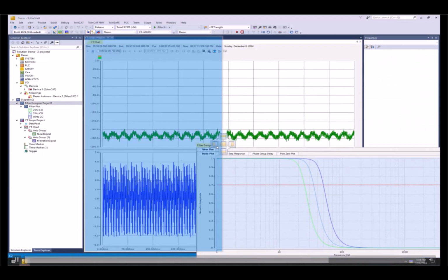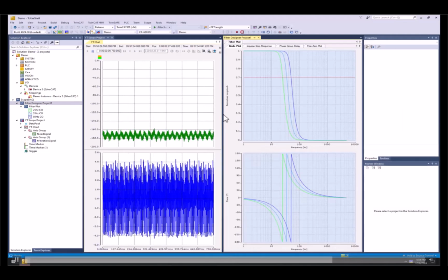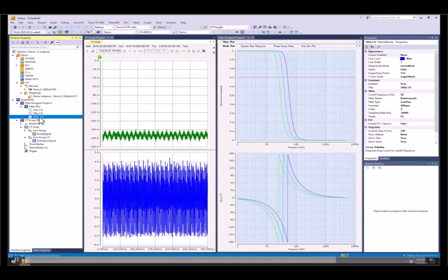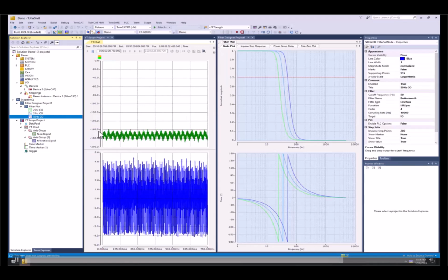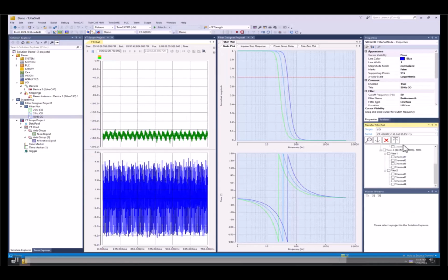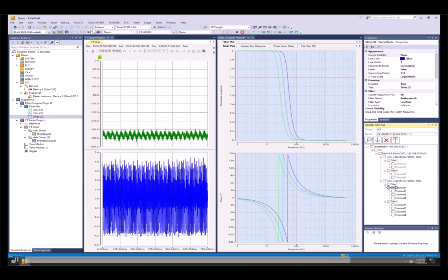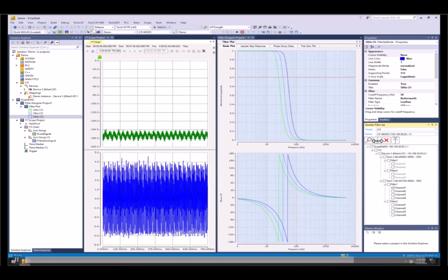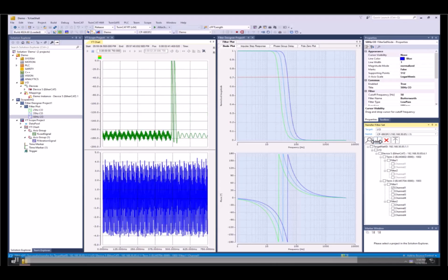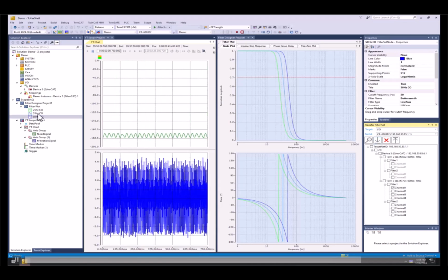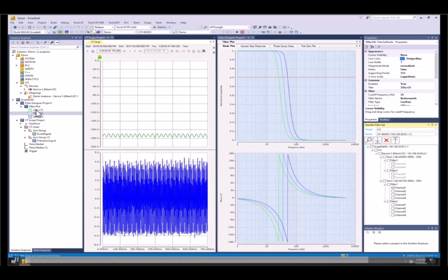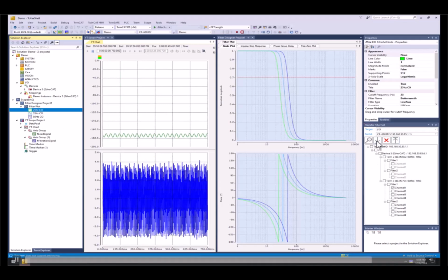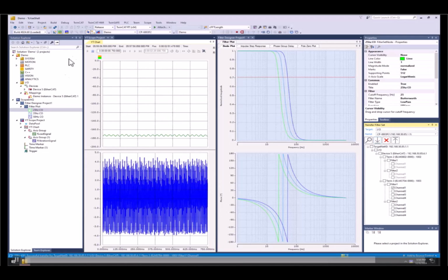And so now I'll drag and drop side by side our filter designer right along with our scope project as it's running. And I'll go ahead and directly apply to the specific channel this design filter. And I'll just kind of go through starting from 50 hertz all the way down to 25 hertz. And so we can see live, I am still actively pushing all of these filters while the data is incoming.